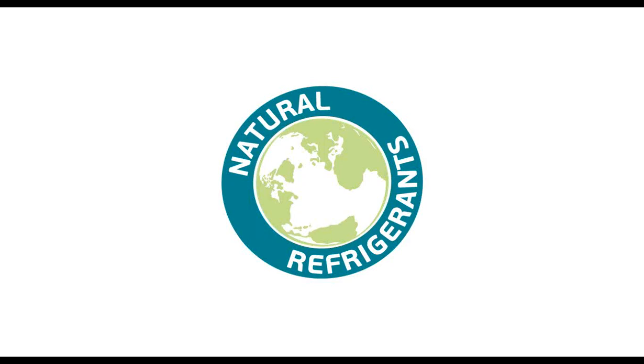We have another question. Can you tell me about the pressures of these refrigerants? Yeah, R600 is a very low pressure gas. It's a little bit lower than R134A. I'm drawing from memory here. At 20 degrees, it's around 3 psi, and it pulls into a vacuum right around 8 degrees Fahrenheit. And then at 130 degrees Fahrenheit, it's around 100 psi. So a pretty low pressure gas. So if you have a leak in the evaporator, it's actually going to pull outside air into the system.